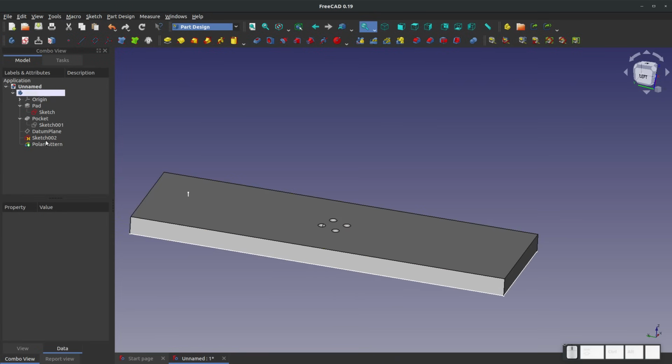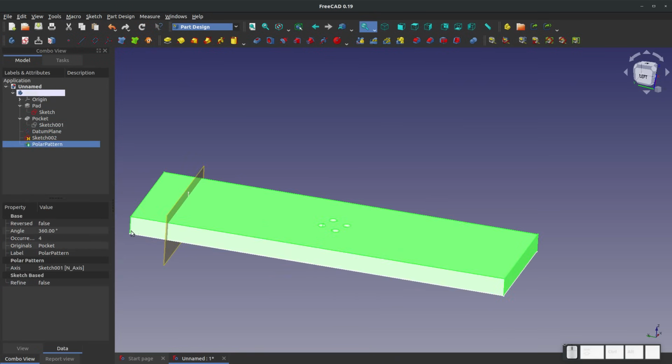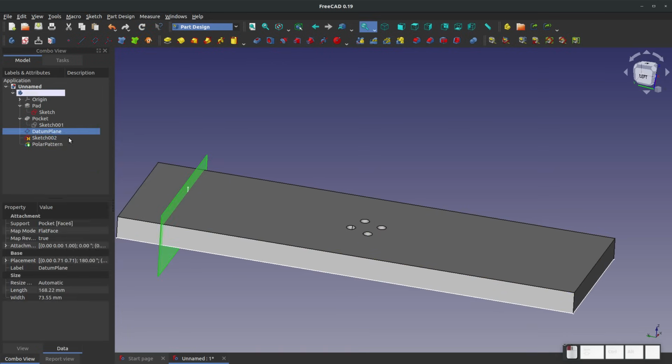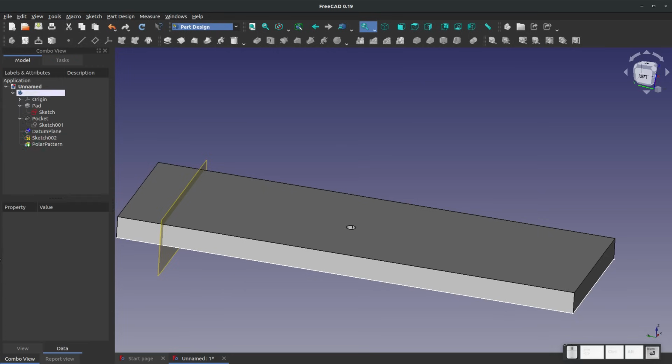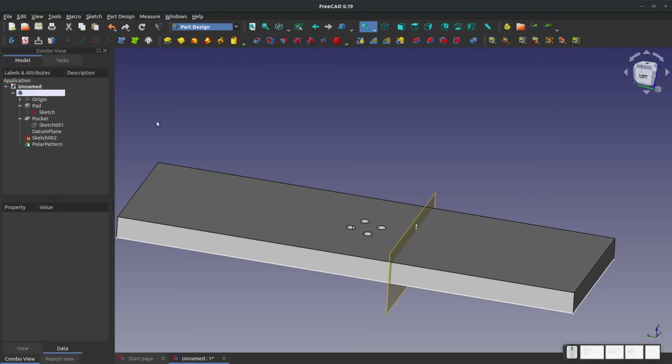Oh, and then it went the other distance, of course. And let me just show my plane with the space bar. Great. So I show my plane with the space bar, edit my datum, and we're going to say 200. And then this little button right here means regenerate. So this line is drawn on this plane, but this plane moved. And so I have to update some of the changes that I made. So when I click update, my line moves back onto my plane, right?